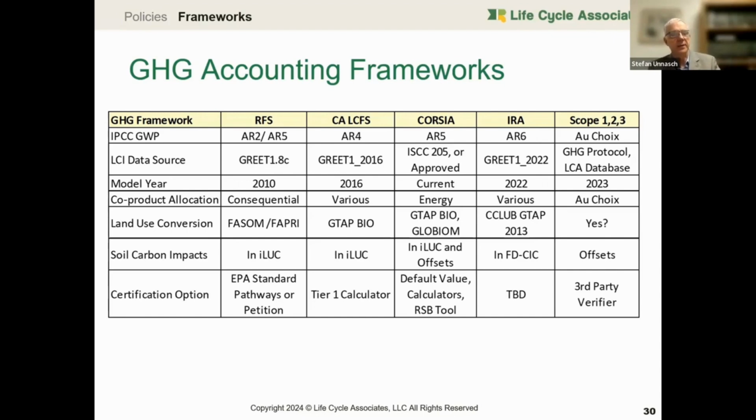And so a kilogram of jet fuel has about 43 or 44 megajoules. Typical petroleum jet fuel has about 89 grams of carbon dioxide equivalent per megajoule. Now, some of the combustion of jet fuel is N2O and methane, but it's a very small part. That's why these IPCC factors matter. But it matters much more because nitrous oxide is a very strong greenhouse gas.